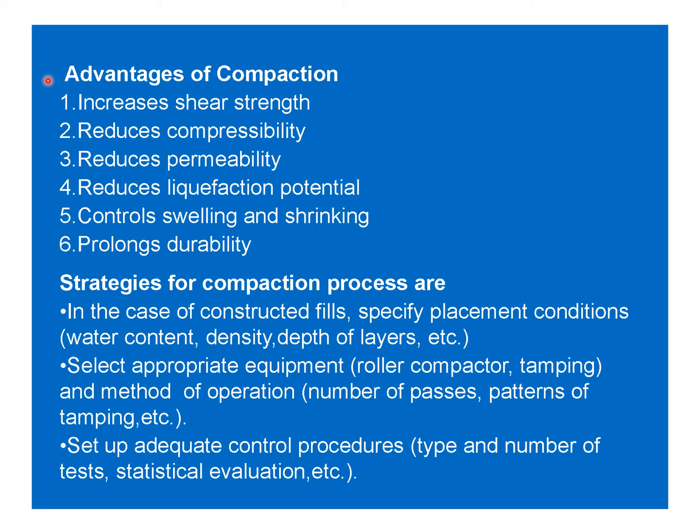Advantages of compaction: increases shear strength, reduces compressibility, reduces permeability, reduces liquefaction potential, controls swelling and shrinking, prolongs durability.